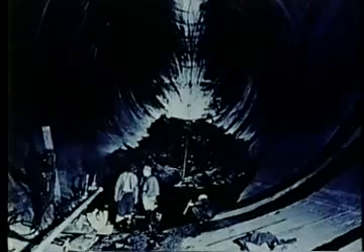Similar damage can be produced on pump parts, such as this impeller of a pump for high-temperature liquid sodium, and in the low-pressure regions of hydraulic structures, such as this large power dam spillway tunnel. There has even been speculation that brain damage can be produced by the collapse of bubbles in the cranial fluid when the skull is accelerated under the action of a sharp blow.